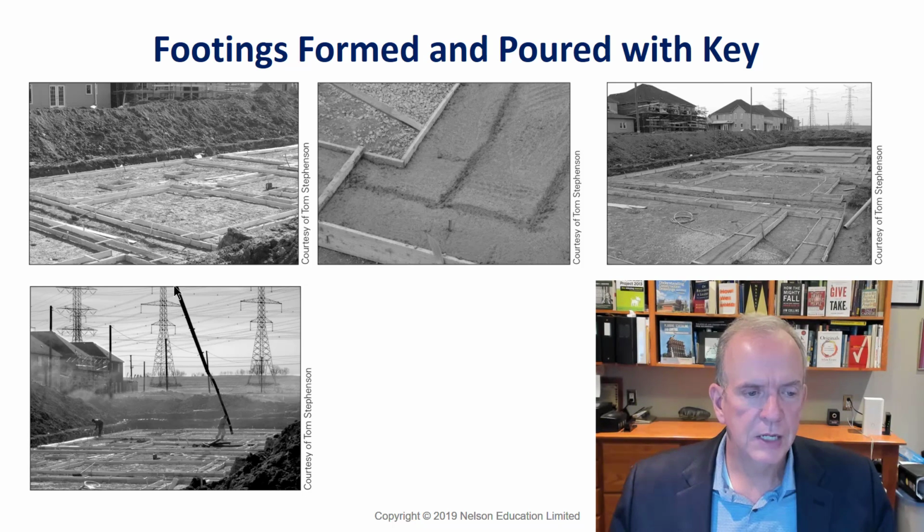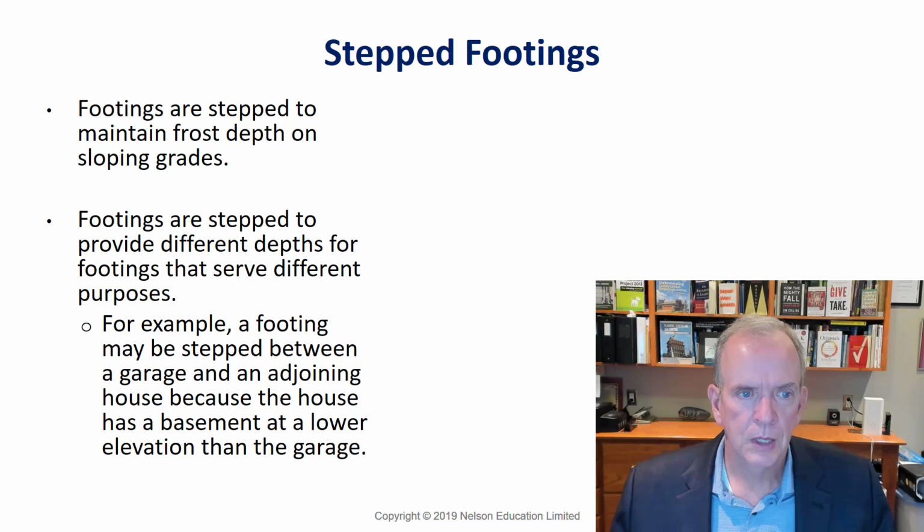So in this case here, they've got a concrete pump and boom, and they're able to move and have the concrete pour out into the footings and then level it as it comes. And they're able to do this in a very efficient, productive manner. In low-rise residential, you might be able to pump it. You might have to wheelbarrow it in. It just depends. Renovations, very often you have to wheelbarrow things.